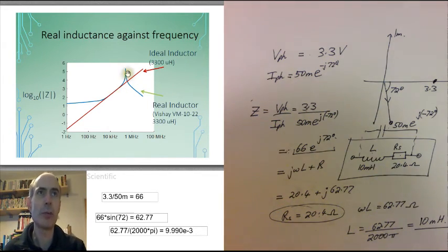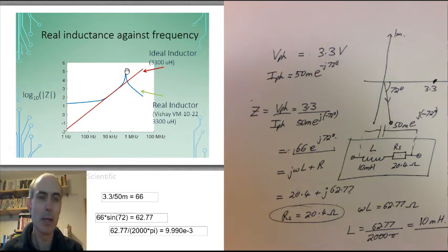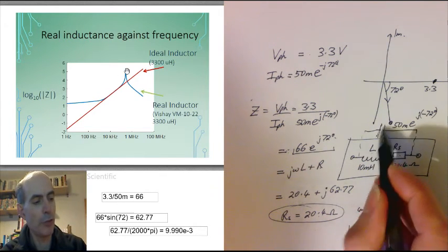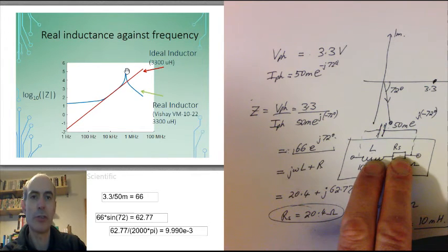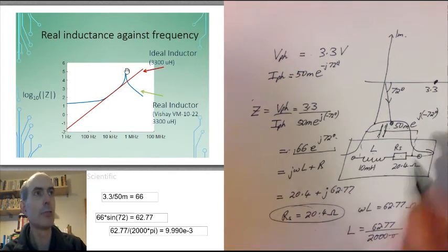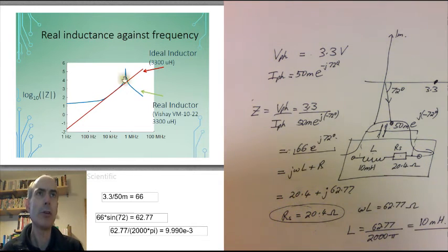And at a particular frequency, known as the resonant frequency again, the impedance of the component has a maximum. Above that point, the impedance of the capacitor is smaller than the impedance of the inductor and the resistor in series. Most of the current flows through the capacitor rather than through the inductor part of the model, and the component starts to behave like a capacitor.